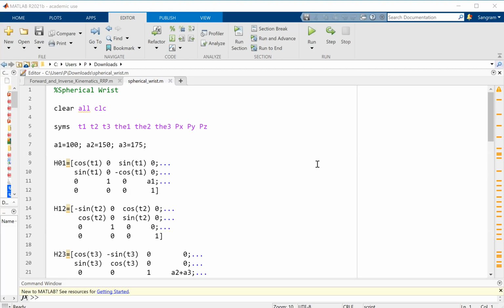The first and the third revolution represent the same degree of freedom. That means you have a gimbal lock. Even though you have three revolute joints, out of those three revolute joints, two revolute joints do the exact same thing, which means 1 degree of freedom is gone.